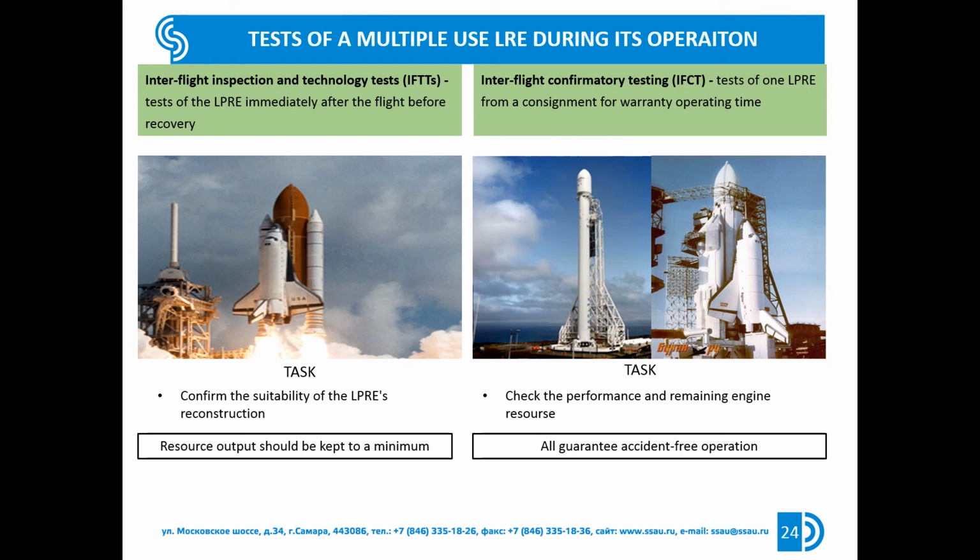Inter-flight technology validation tests are performed on each LPRE immediately after the flight or necessary remedial work is performed. As a result of these tests, information on the technical condition of the liquid propellant rocket engine should be obtained, which allows the conclusion to be made on its compliance with the design documentation.